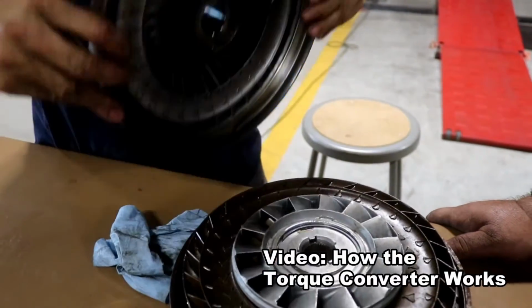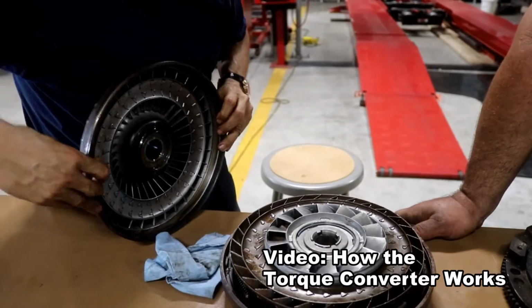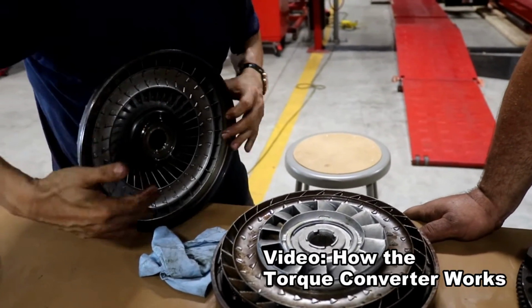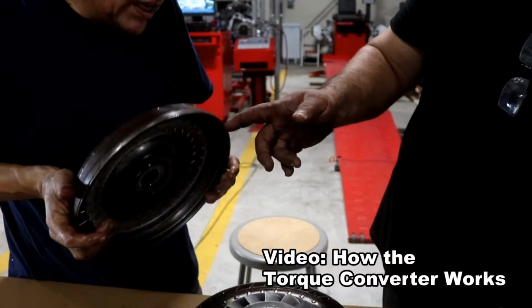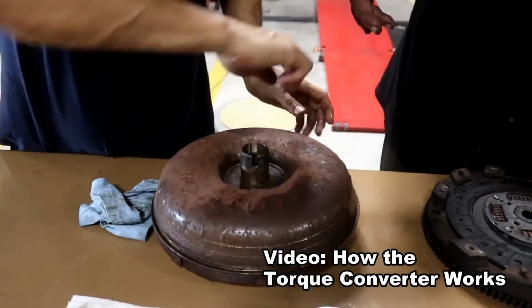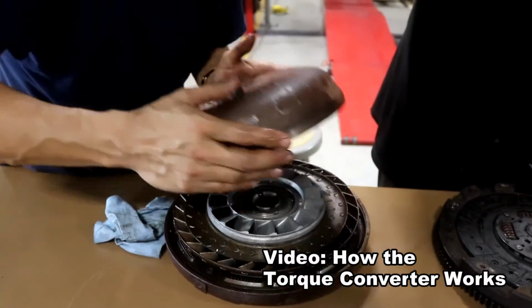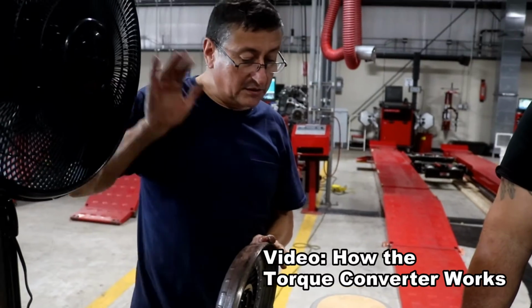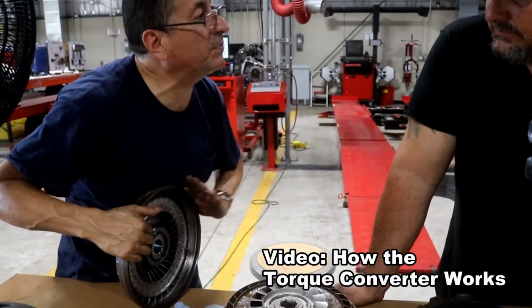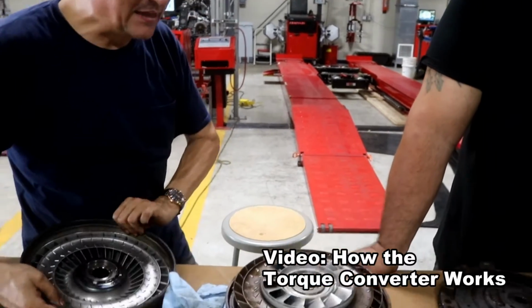This is part of the housing, and this turbine is welded on this housing. This is the one that's constantly moving, because this is solid and attached to the flywheel. So that's the one that moves. It's like that fan you were talking about. This first one is the fan, because it's moving at the same speed as the engine, at the same RPMs.